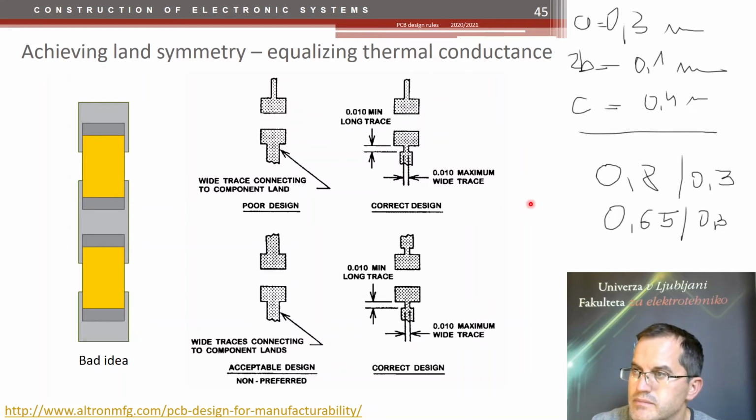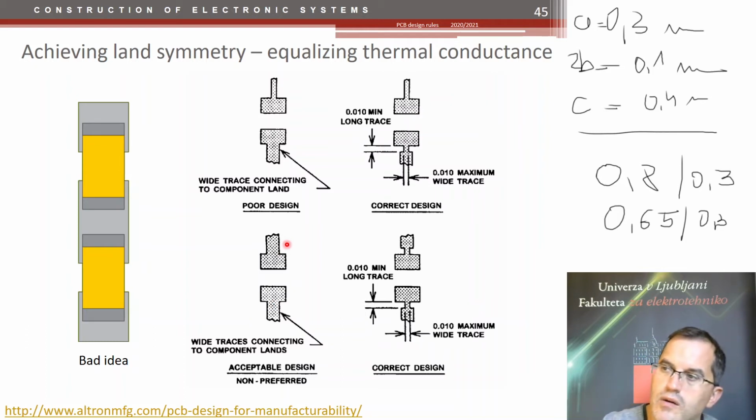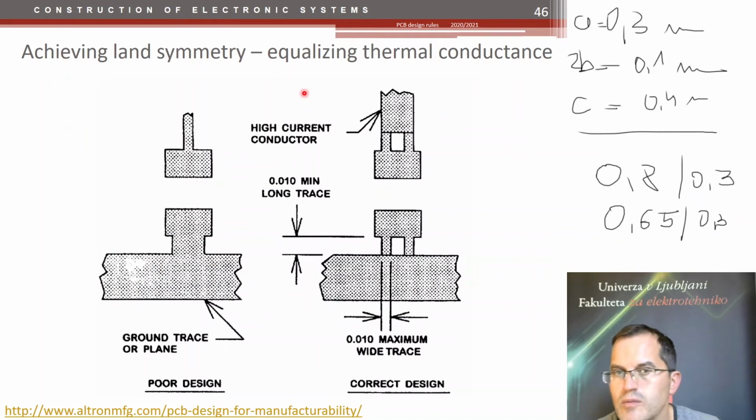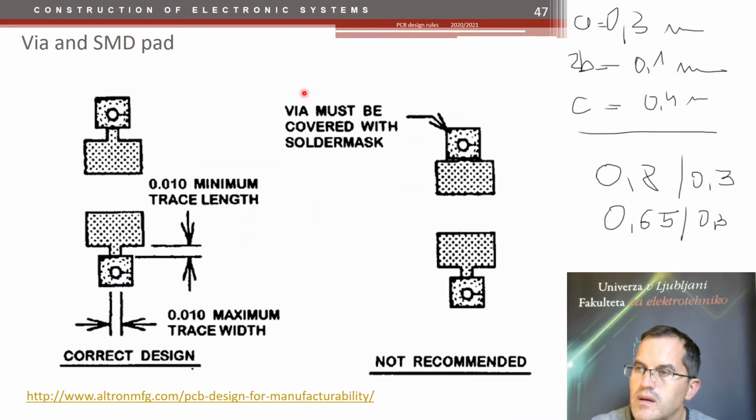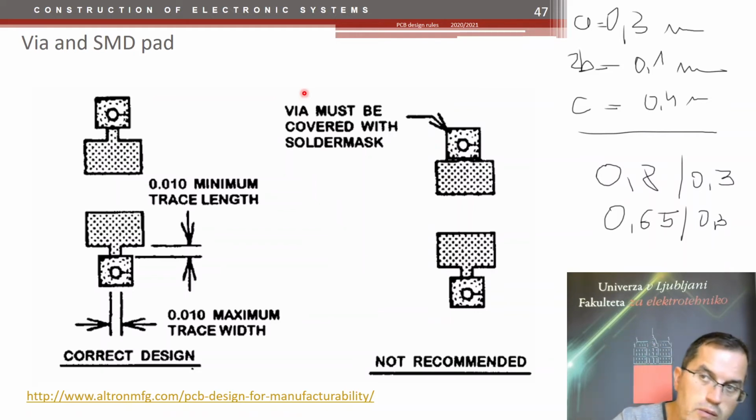And as long as you keep the small part or the connecting part to the pads the same, you're on the right side. Also, this I don't think is that bad. The only, I would say, wrong, poor design is here. If you want larger current, well, you can go with several narrower traces. If you want to use wires and there is a problem, then move them away.